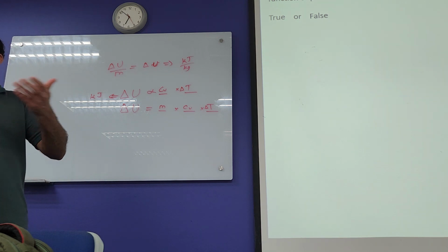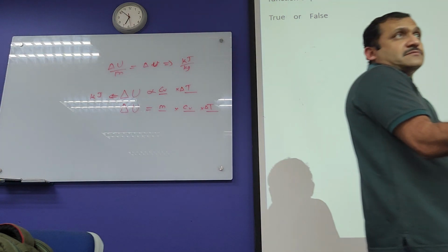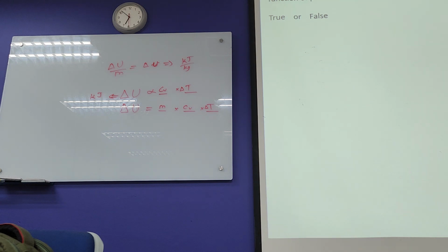The reason why we do that, divided by kilogram, is to make it independent of mass, and then we can use that property to design and scale up and scale down systems. We can start with a very small volume or mass of the system, and then go to a very large one. Same calculation, same logic. It's for the purpose of scaling. So, properties such as specific internal energy and enthalpy, entropy of a substance are functions of pressure, temperature, and specific volume of that substance. Are they functions of those three fundamental properties? True or false? That's true.